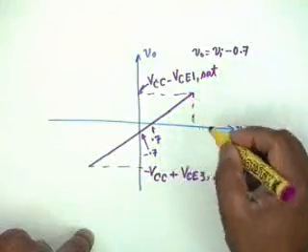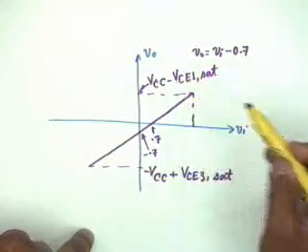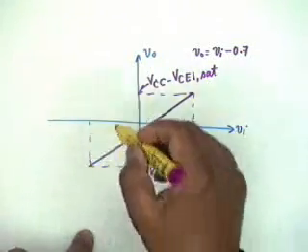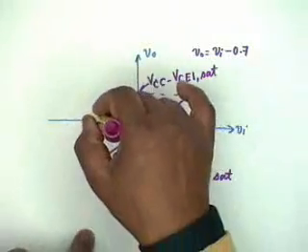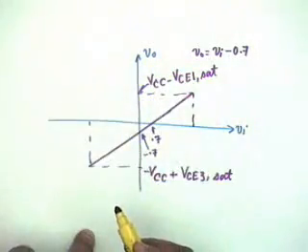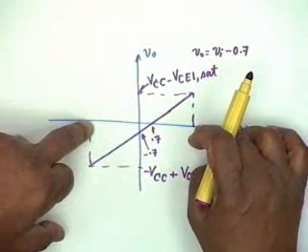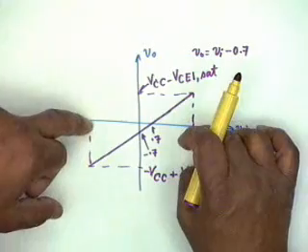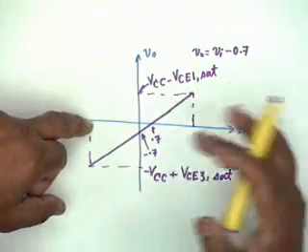your input voltage. What is the input here? Input voltage is this plus 0.7. Similarly, this voltage would be this plus 0.7. Okay. So, you know the input voltages, the input voltage must not exceed these two values, either on the positive side or on the negative side.